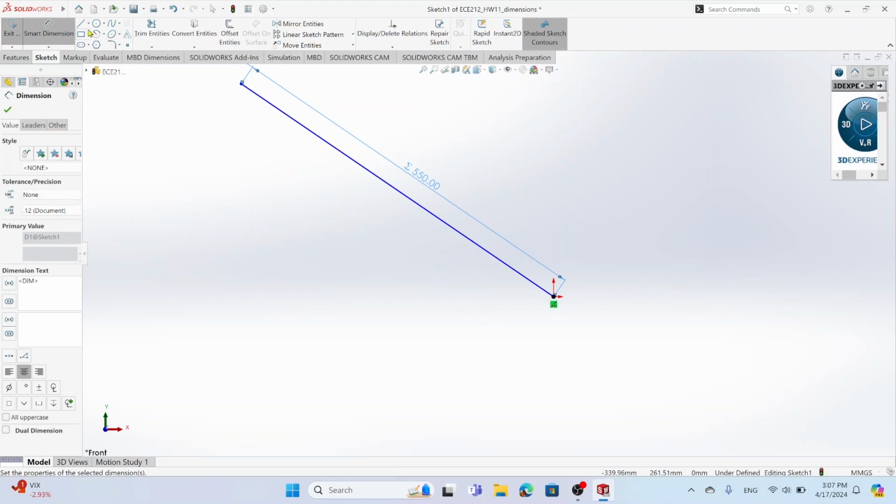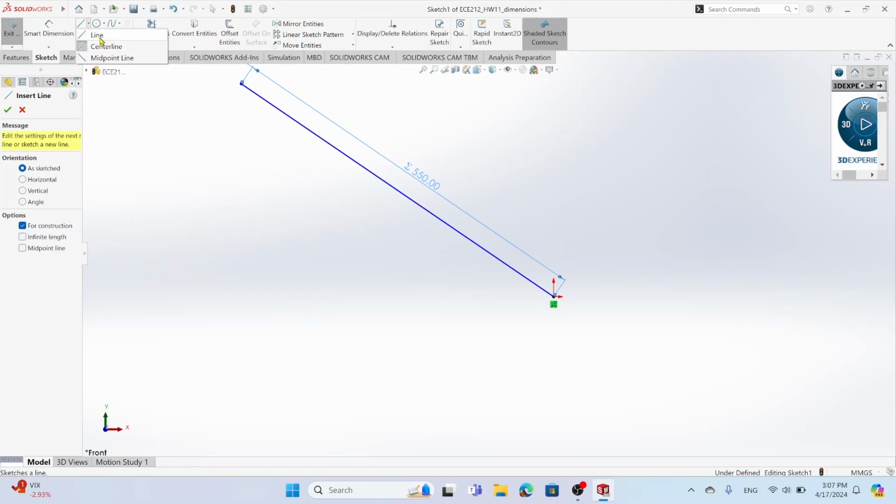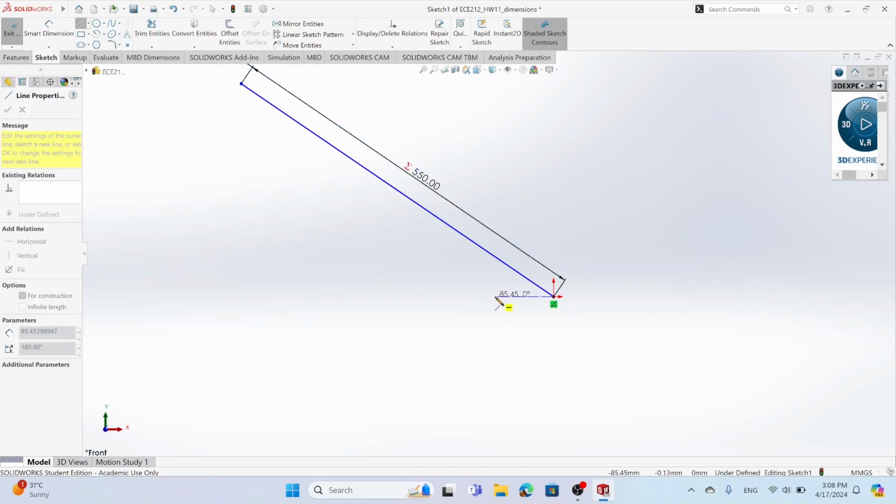You can find your angle, or you can do another way. I don't like to make calculations, so I will select the center line, or you can just select a line and change it afterward, but make sure to put it as a dimension. When you draw it, that will give you those little symbols, this one and one vertical there.